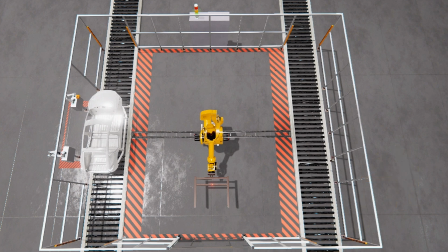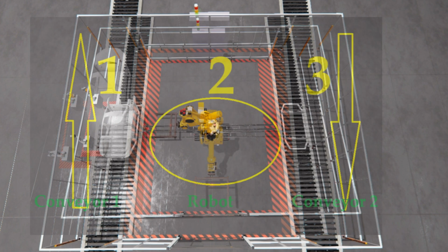Our Do-More product quality verification machine can be broken down into 3 sequencers. Conveyor 1 sequencer will allow car bodies to enter the inspection station. The car body will be positioned at Conveyor 1 stop. A camera on the collaborative robot is used to determine if the car hood is present or not. If present, the body is marked by a second collaborative robot and sent out to the inspection station.